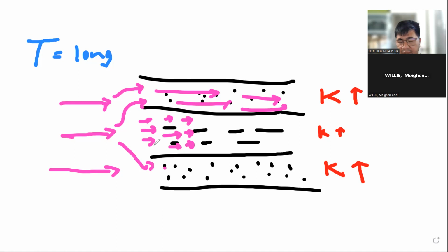This flow path can easily divert through the faster sand layer. Okay. And this will result in a more efficient flow of water through the bedded layers, as long as the flow path is parallel to the bedding planes. Okay? Therefore, your time to flow through this layer will be relatively shorter.